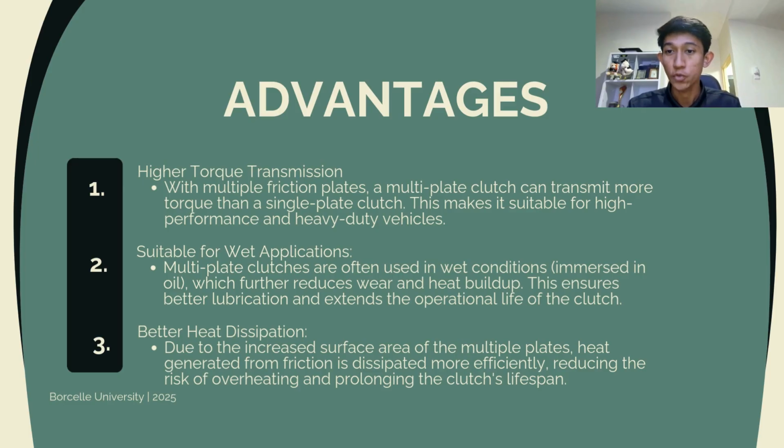And next up, we have suitability for wet application, which is often used in wet conditions, as an example, immersed in oil, which further reduces wear and heat build up. And last but not least, for the advantages, we have better heat dissipation, which is due to the increased surface area of the multiple plates. The heat generated from the friction itself is dissipated more efficiently, reducing the risk of overheating and prolonging the clutch lifespan.